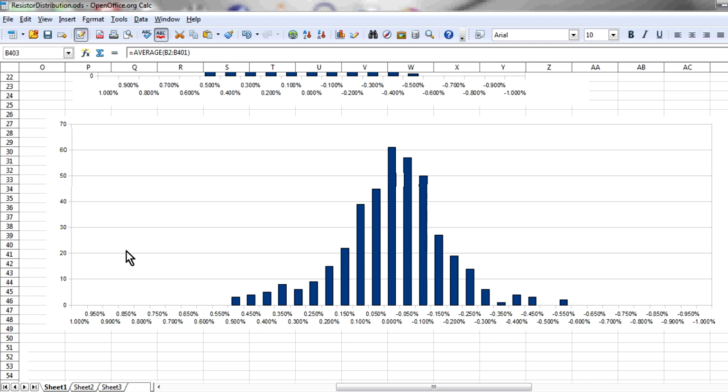So it would have been much flatter, and we would have seen a reasonably large number of resistors out here at the 1% limits. And if you get the cheap no-name resistors, you buy them off eBay and you measure them, then they could very well be 5% resistors tested as 1%. Who knows? I don't know. Maybe they don't do that anymore. Maybe it's a myth these days.